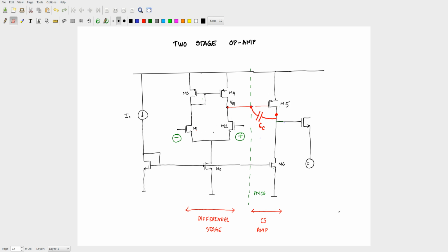So instead of having that current source here, we can have that. And what should I have on top? Nothing, right? And where should I take my output? Here. Okay. So this becomes your common drain amplifier, which acts as a buffer. Okay. So this improves your output impedance.